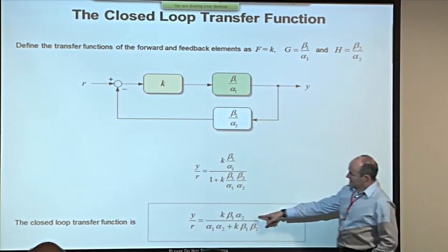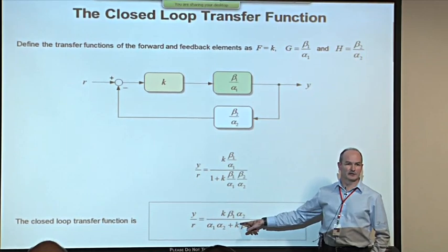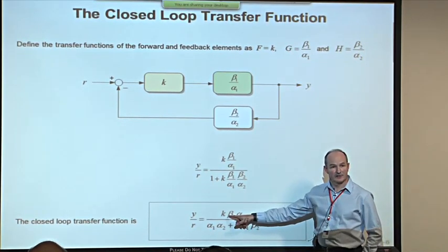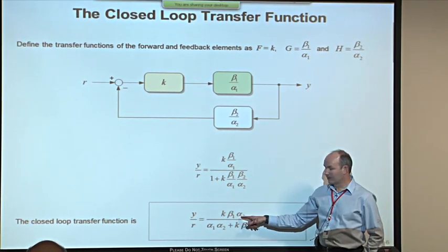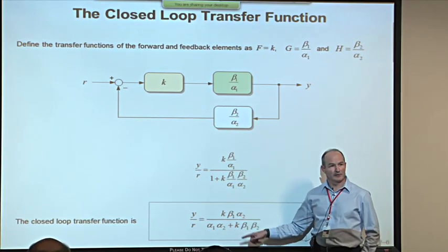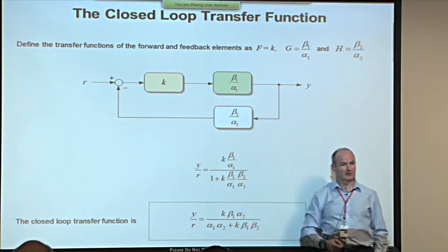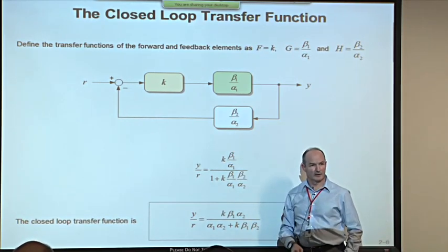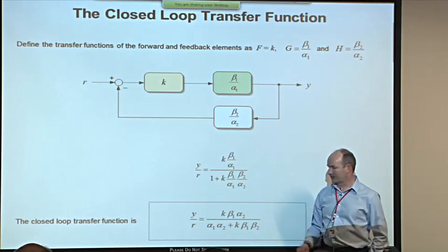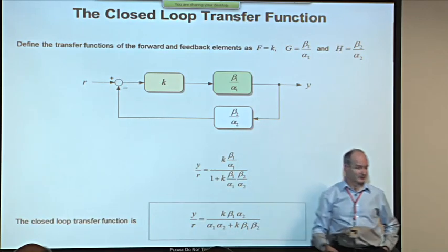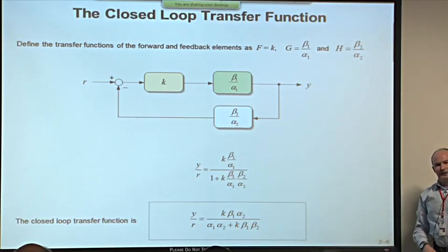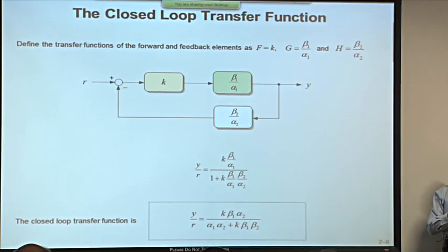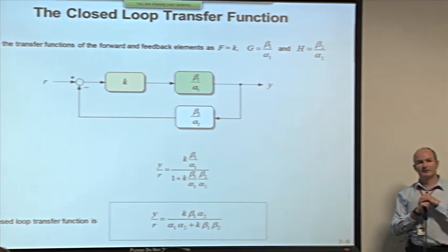Well, the closed loop zeros are pretty easy to find. They come from the zeros of the plant and the poles of the sensor. Anything which is a zero in the forward path is also a closed loop zero. Anything which is a pole in the feedback path is a closed loop zero as well. Pretty easy to find out where the zeros are, as long as you know these transfer functions. Now, the zeros, of course, contribute to the residues of the time response, but they don't influence the stability of the response. It's the poles that tell us the stability, together with a lot of other information.